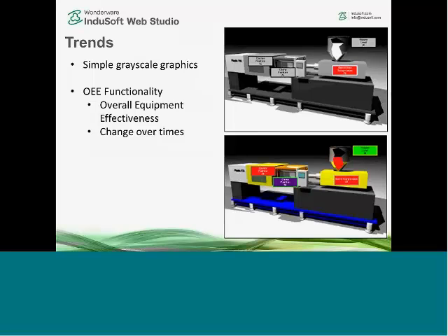Another concept is overall equipment effectiveness, or what's known as OEE. And this functionality is really used throughout the packaging industry and manufacturing industry to be able to monitor equipment. And if it's, let's say, supposed to be, at least here in the U.S., running for an 8-hour shift, and it's only running for 6 hours, well, what is it doing for those other 2 hours?